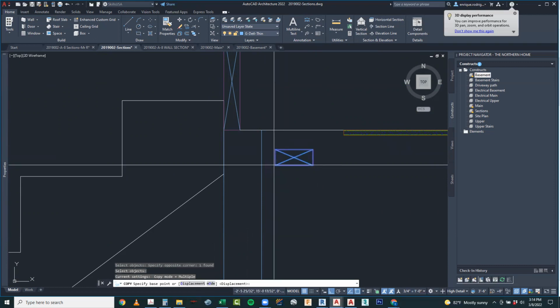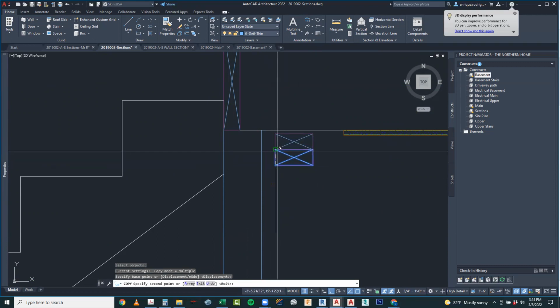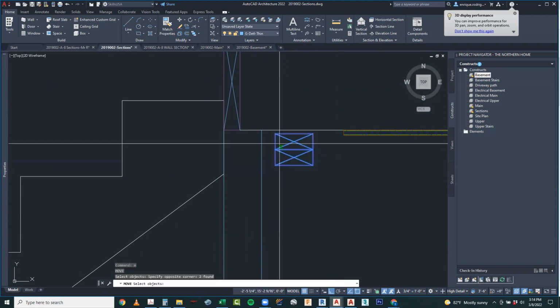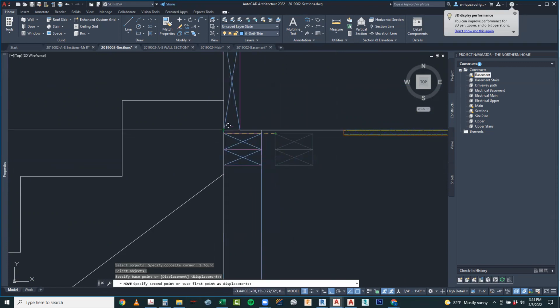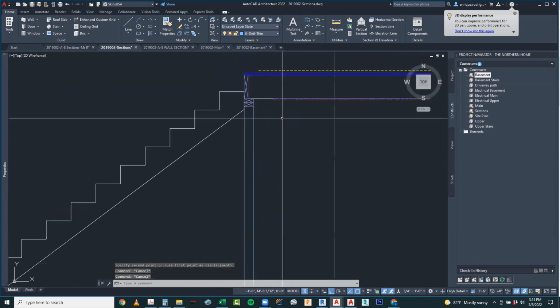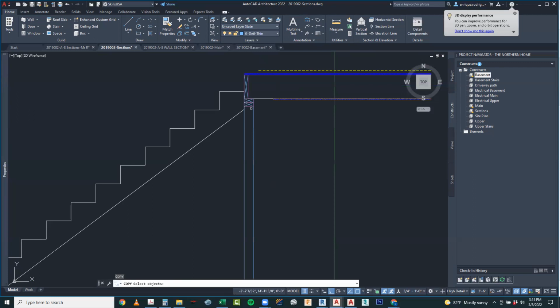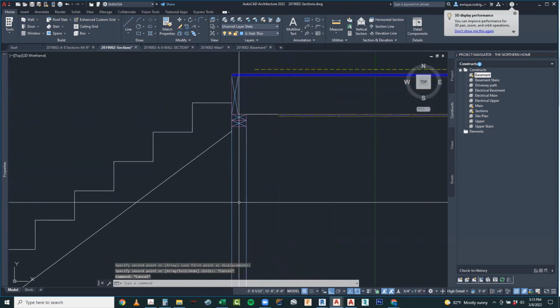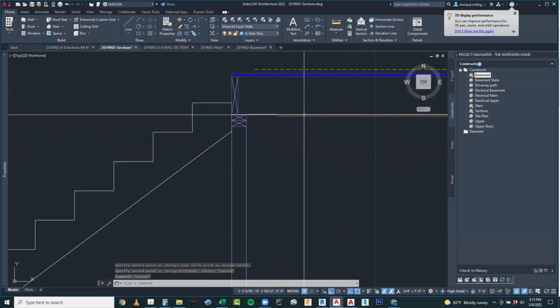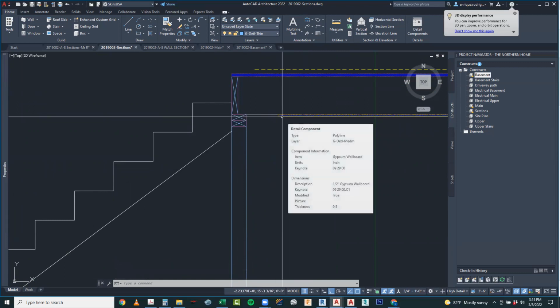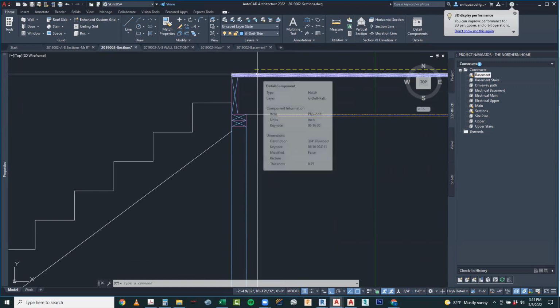I'm going to go ahead and copy it because we do need 2 plates at the top. I'm going to move this guy from here to here. And then we need a sill plate or a sole plate at the bottom. So I'm going to copy this from there down to here. I'm not putting any additional finishes on this yet. Notice I've already got the drywall, which I brought in from my other wall section, and I brought in the plywood.